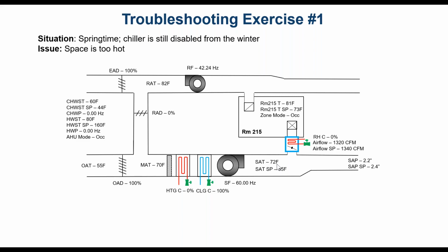All right, so we have to go back to step 3. Is that variable in question, now the supply temperature, being controlled for? Yes, we know from the sequence of operation that there are several different things which are controlling the supply temperature. We have these dampers, the heating coil and the cooling coil. All right, so let's investigate those various control loops. Is the set point appropriate? Is the supply temperature set point of 55 appropriate? Yes, it is. That's what the system was designed for.